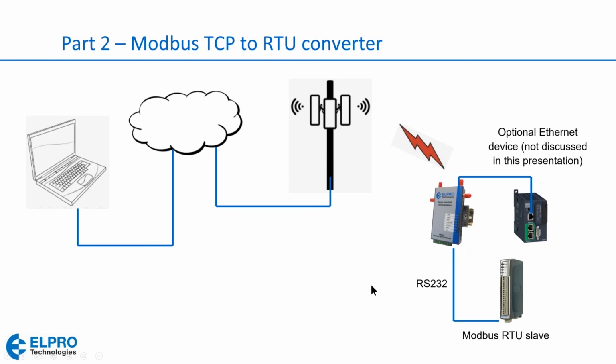Now, we also make an Ethernet expansion module, the 115E-2. And of course, you can connect that directly to the Ethernet port on the cellular modem. So there really are two methods of doing so. But in this case, we wanted to highlight Modbus RTU because it uses serial ports, and there really are thousands of Modbus RTU devices out on the market.